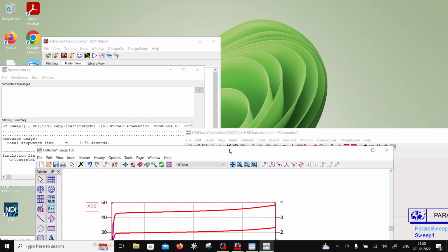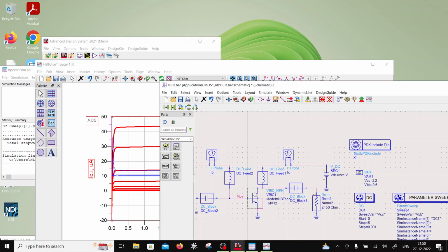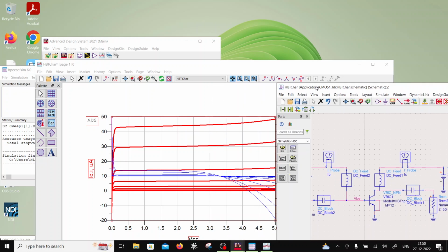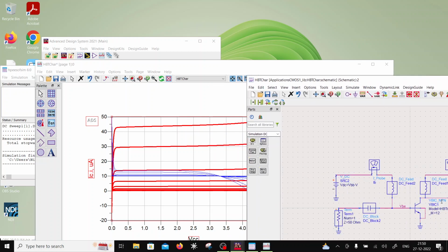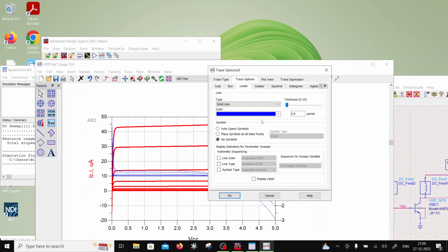Now what I told you was that at 3.3 volts, the collector base junction is going through breakdown and the reverse leakage current is basically now being collected by IB, right? So that's why it shows up as IB as a negative current, because VBB is basically collecting that current. The current is not flowing into the base emitter junction, rather it is all collected by this supply. So you can see the difference, you can see basically what's going on when the collector base junction goes into breakdown.